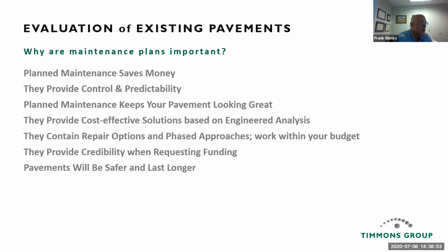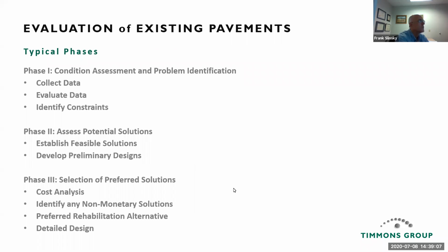They contain repair options and phased approaches, work within your budget. They provide credibility when requesting funding. Pavements will be safer and last longer. So here are the typical phases of a pavement evaluation. Phase 1 is when you do a condition assessment and problem identification.